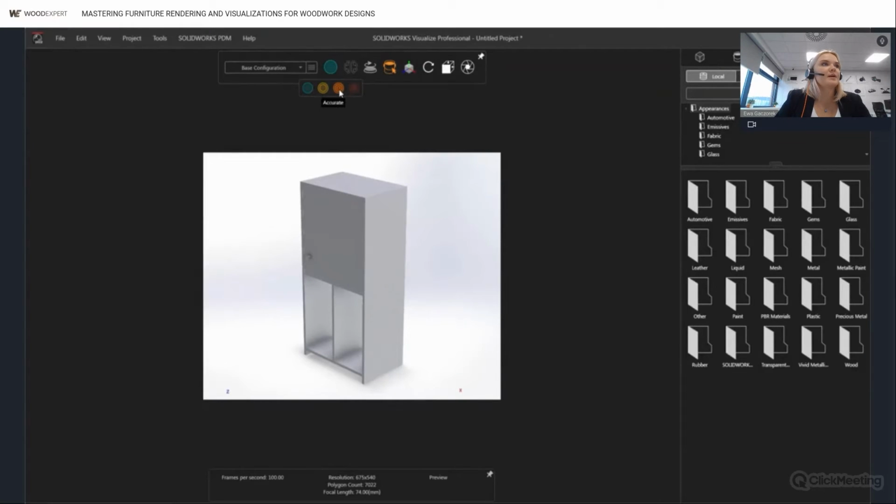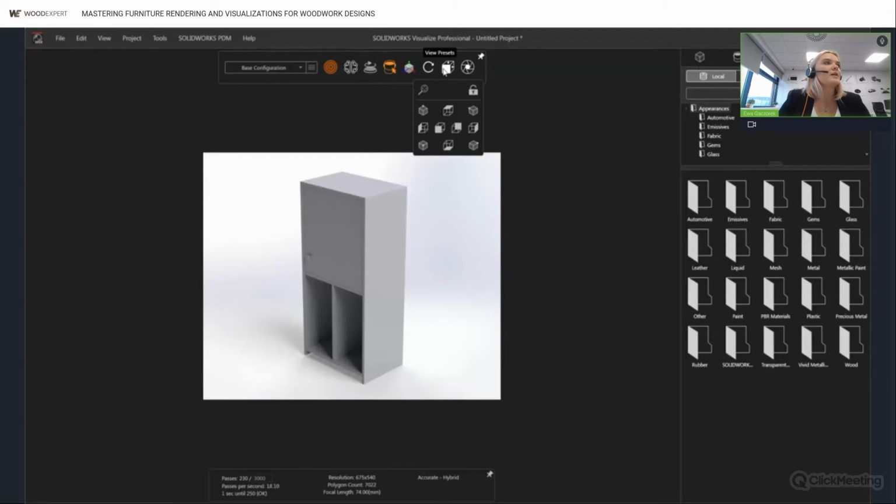So I will now discuss the interface. The top palette shows how the model is displayed, from preview to exact view. The more advanced the preview, the longer it takes to recalculate the model. In the case of furniture, it does not take long. When working with a large assembly, it's better to work in preview mode most of the time. Further functions in this panel are model rotation, part rotation, and view changes. When I'm working, I use the mouse and scroll rotation. Most often during the work, we use the model preview changes and possibly change the location of the workspace.